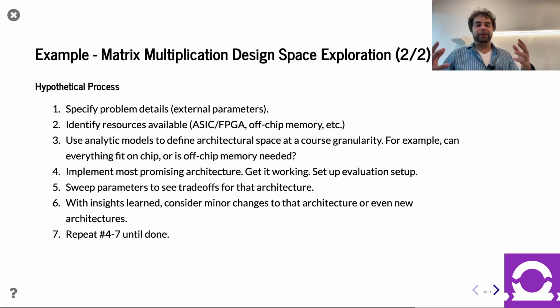So number one, specify the problem, the external parameters. Two, figure out what you're going to build this with, what kind of things are in your budget, if you have to use off-chip memory, what kind of bandwidth and interface you're talking about, that kind of stuff. Now, even though I told you a second ago about using an agile process, I still think there's some room for analytic models really early on, but I want to emphasize, this is an afternoon's worth of work with a whiteboard, right? It shouldn't be a super sophisticated thing you run for a long time. It's just back-of-the-envelope kind of math.